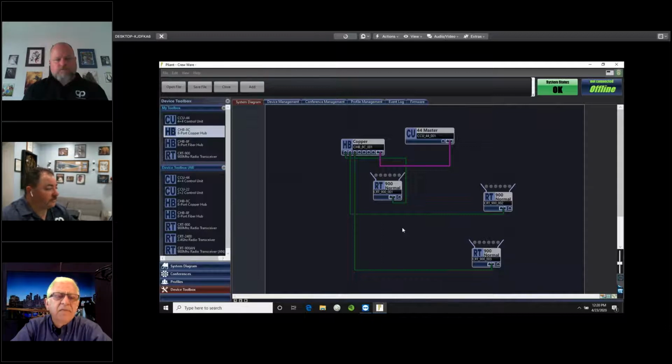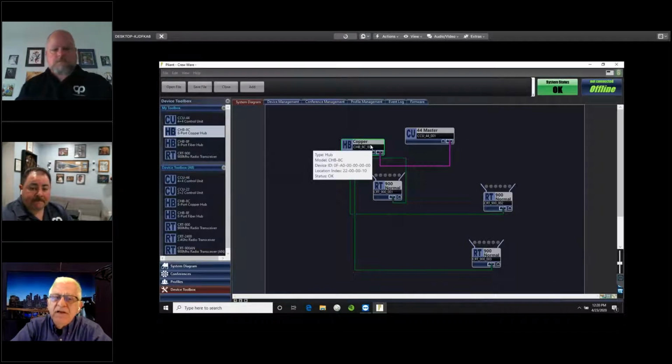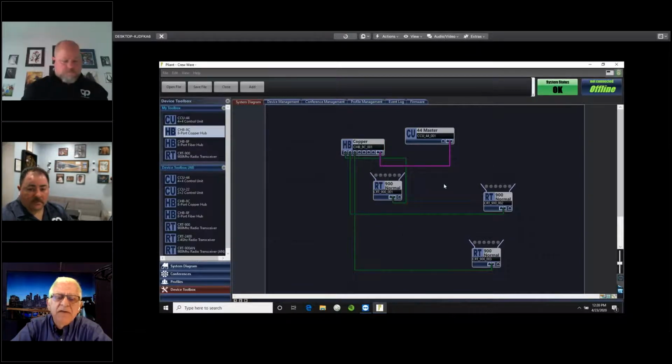Okay. And again, that hub needs to have the same power supply that you would put on an antenna to run it. Correct. Now, I do have a question from Jason Glass: can you use PoE injectors to power the antennas? The copper connections always have PoE on them. There is a 48 volt PoE coming through them from all the various power supplies. But standard PoE injectors won't work. It has to be the CrewCom hubs or antennas to supply it. Correct.